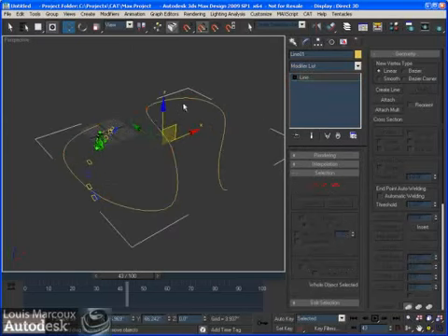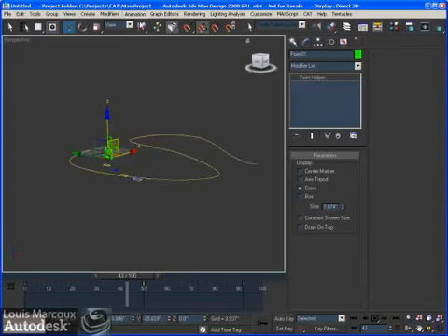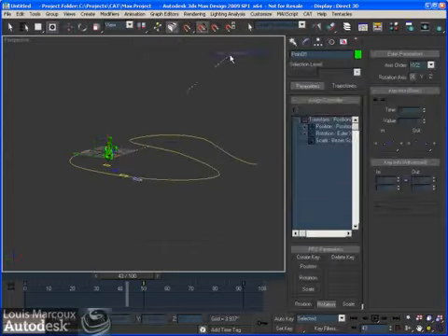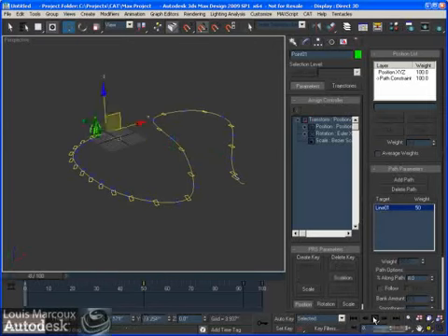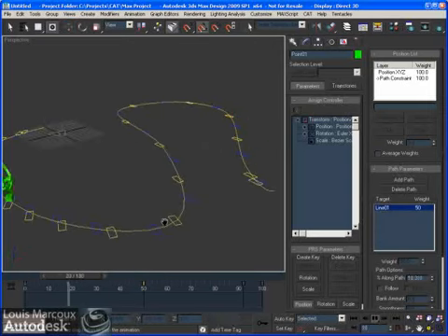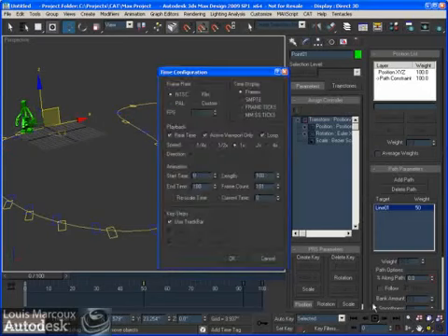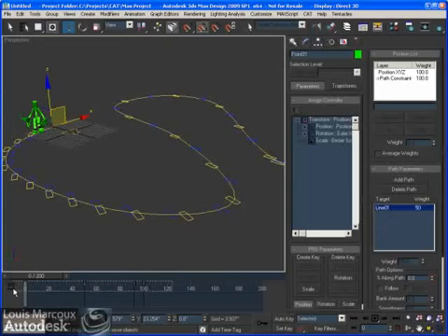I've created a smooth line, and now what I can do is grab the actual point helper and say Animation, Constraint, Path Constraint, and constrain it to that path. So now it's fully constrained to the path, so it's going to be animated like this, and you see that the character is trying to follow. Now it's way too fast. What I'll do is adjust the time, maybe to 200, so that it's a bit slower, and I'm going to delete all of the keyframes here.